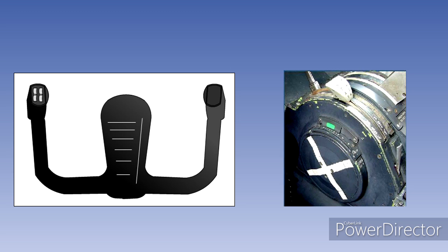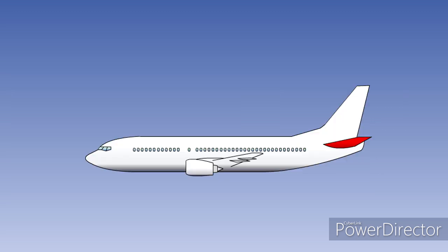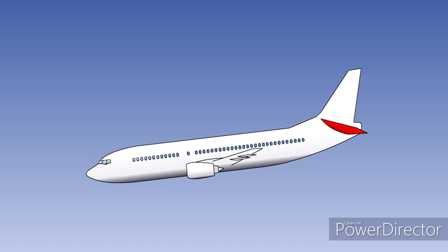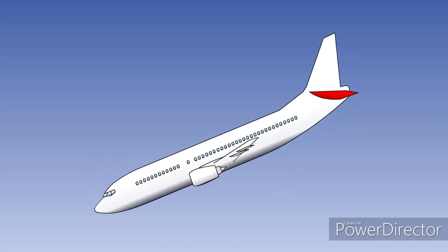And as a pilot, this is how you always use them. Consider them to be a single switch or lever. The reason why there are two switches and two levers is to prevent the short-circuiting of a single switch or the jamming of a single lever, causing an undemanded trim operation or trim runaway.